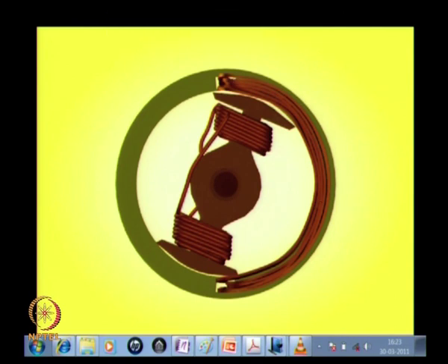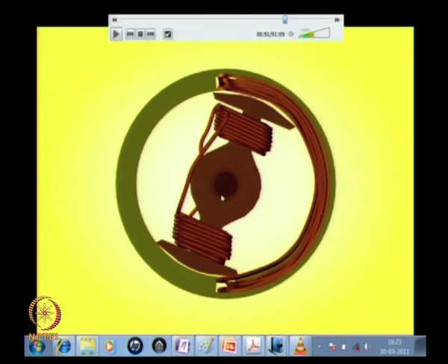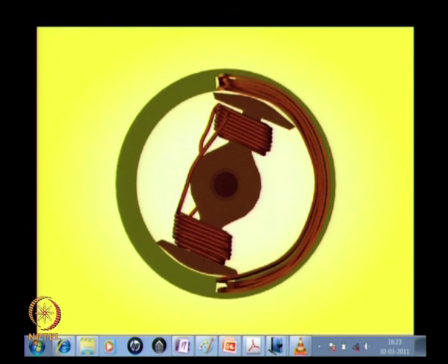Now once the field is excited, this arrangement will produce a magnetic field that circulates through this rotor pole, gets into the stator. One half of those flux lines would go around this stator, come back into this rotor pole, the other half would travel around through the stator again and come back into the rotor pole. That field generated is shown as a blue glow in this animation.